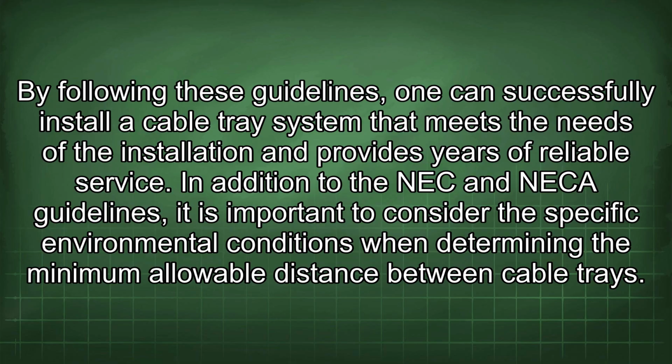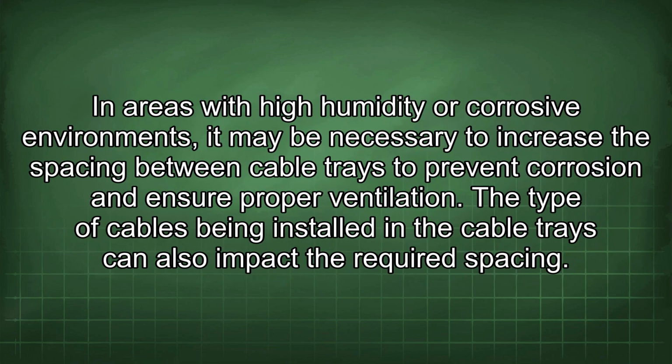In addition to the NEC guidelines, it is important to consider the specific environmental conditions when determining the minimum allowable distance between cable trays. In areas with high humidity or corrosive environments, it may be necessary to increase the spacing between cable trays to prevent corrosion and ensure proper ventilation.